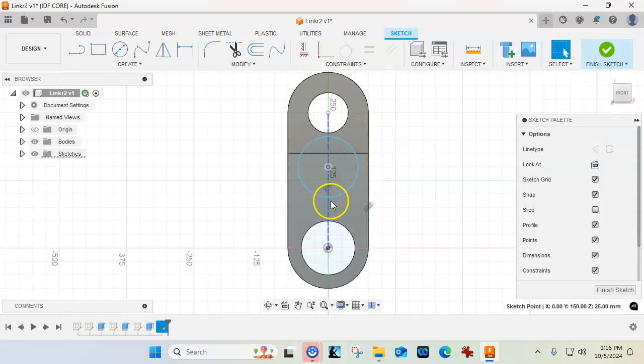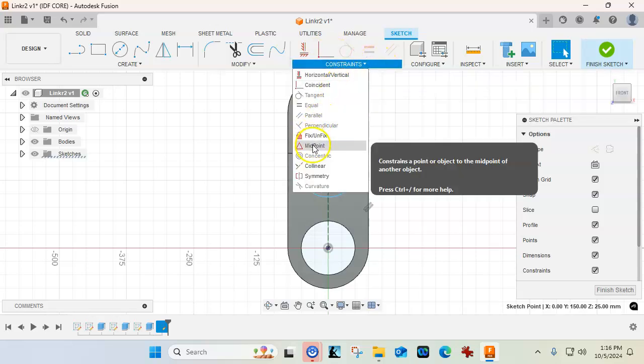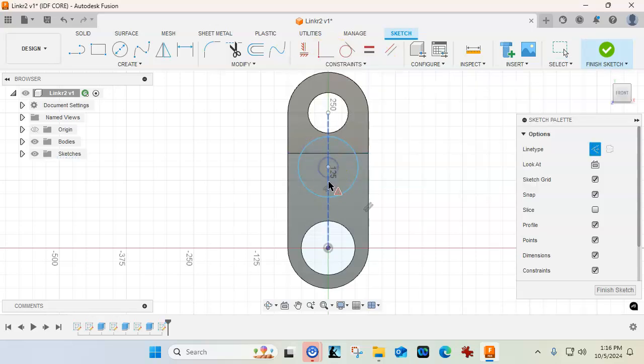And what that's going to let me do is find a midpoint. All right, so make sure that's selected, make sure that's selected. There, it jumped. All right, and then we'll need a dimension. I don't want it to interfere too much, so let's go with an 80 millimeter through hole just for lightening.